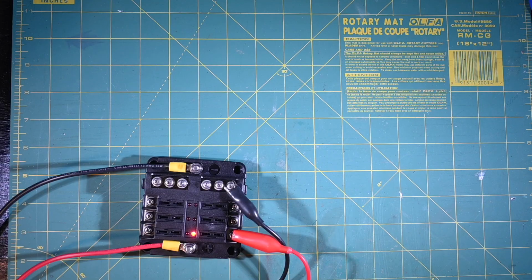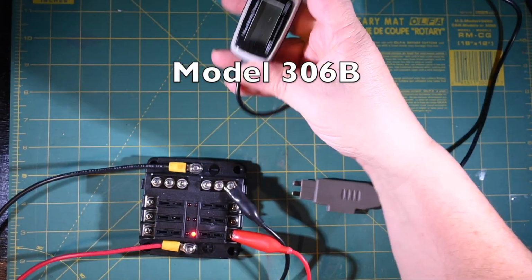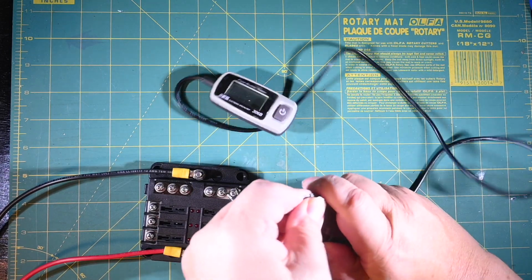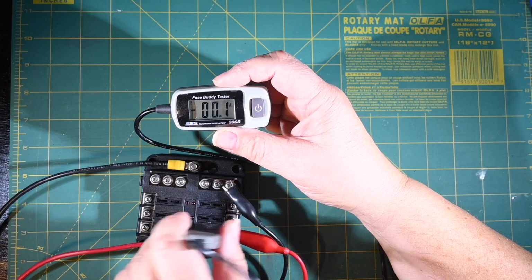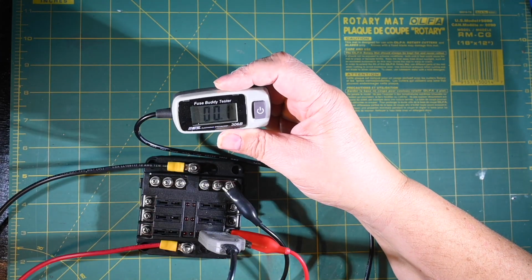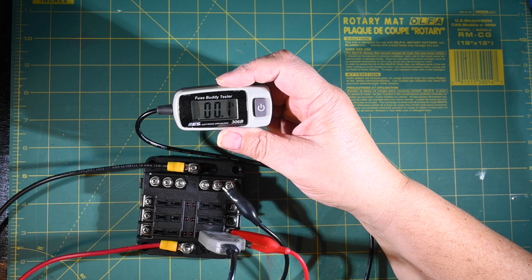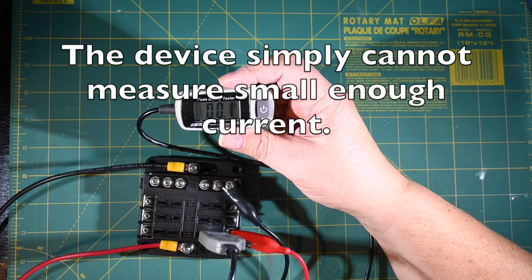But if you don't want to spend that much money, you can buy the adapter standalone. This is around $20. Same thing, you just put a fuse in here and plug it into the circuit. Interesting, this is a minus sign. If you turn it around, the minus goes away. You can see that it measures 100 milliamperes, which is really not all that accurate. This is a 0 to 30 amp tester with a resolution of 100 milliamperes, so the use of this is a little bit limited.